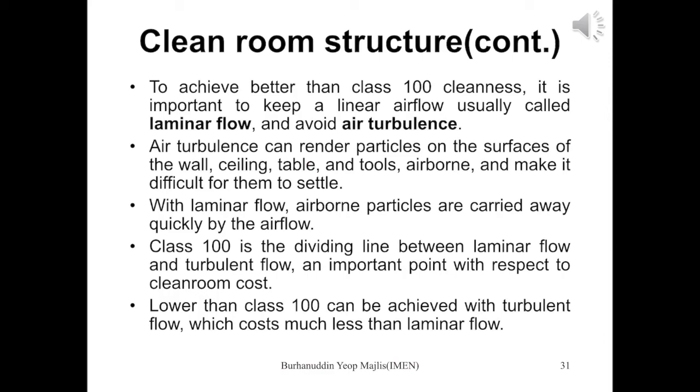An important point with respect to clean room cost. Sometimes what determines which class and which flow type we want is the cost also. Lower than class 100 can be achieved with turbulent flow and costs much less than laminar flow. To make laminar flow is more expensive than just turbulent flow. So we have to think about what we want to do with the clean room, whether we have to use laminar flow or it is not necessary. We can use turbulent flow also as long as we can achieve what we want.